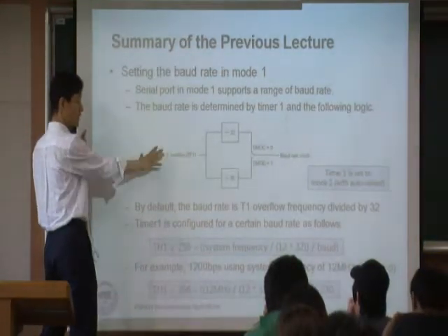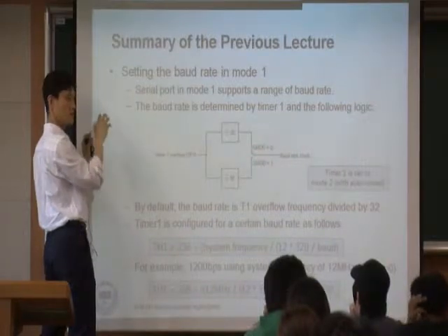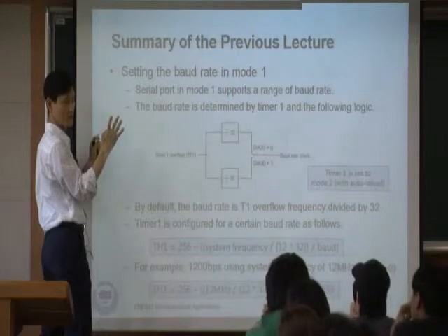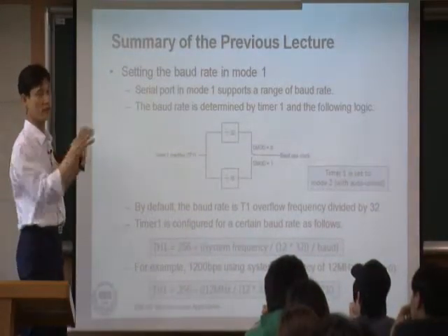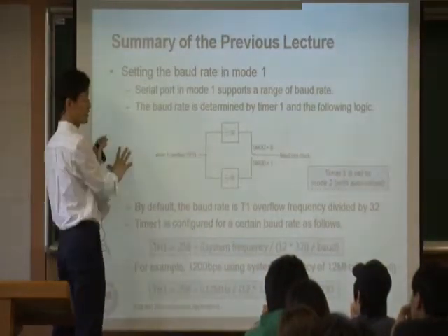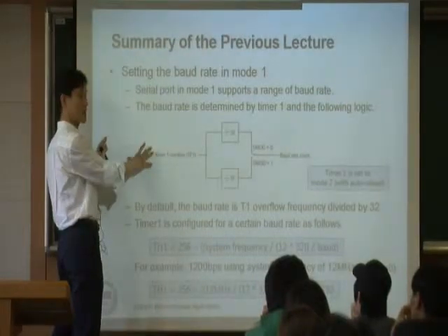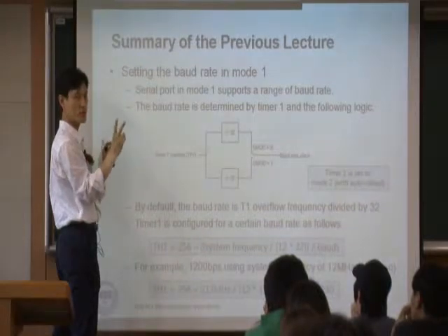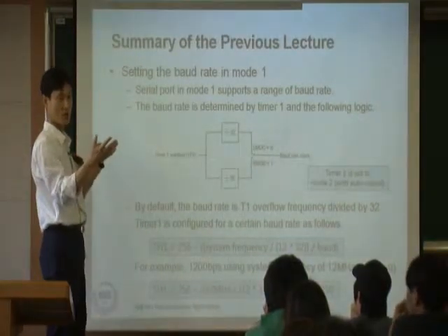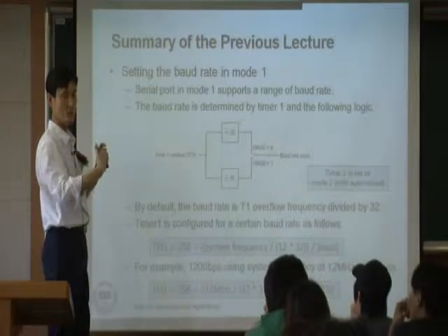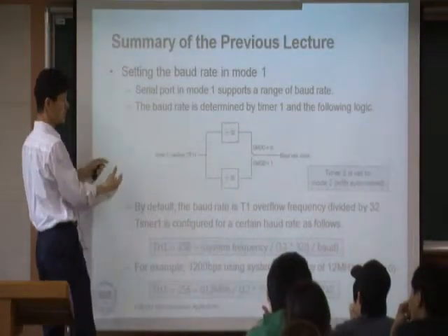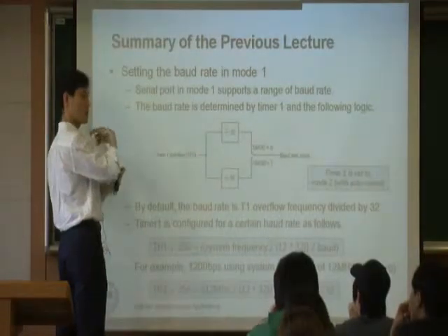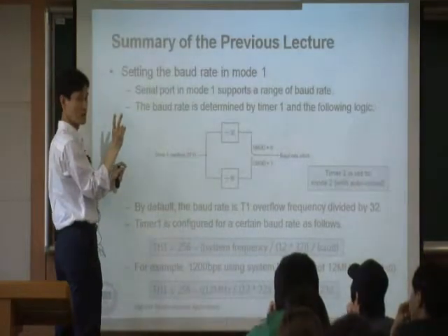In timer hardware, what you need to do is set what timer mode you want to run it. There are 4 different modes, right? Mode 0 to mode 3 in timer. Especially in timer, you want to run this timer with mode 2. Why is that? Because mode 2 timer has a very nice feature called auto reload. So you need to set the initial value for the timer and then run with mode 2, right?